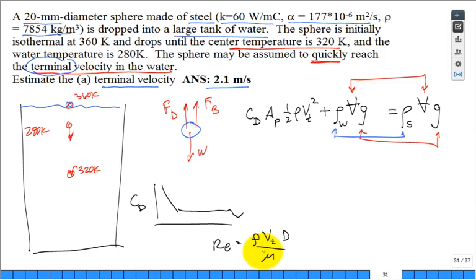So what you do is you probably would assume a drag coefficient, because it seems like you're probably in this range of Reynolds number. So you go back and you say, I don't know, drag coefficient's about 0.8, 0.1. No, that's too low. 0.4. Okay, somewhere in that vicinity. And then you would actually solve for the terminal speed. Then go get the Reynolds number. Then come in and update your value of C sub D. All right.